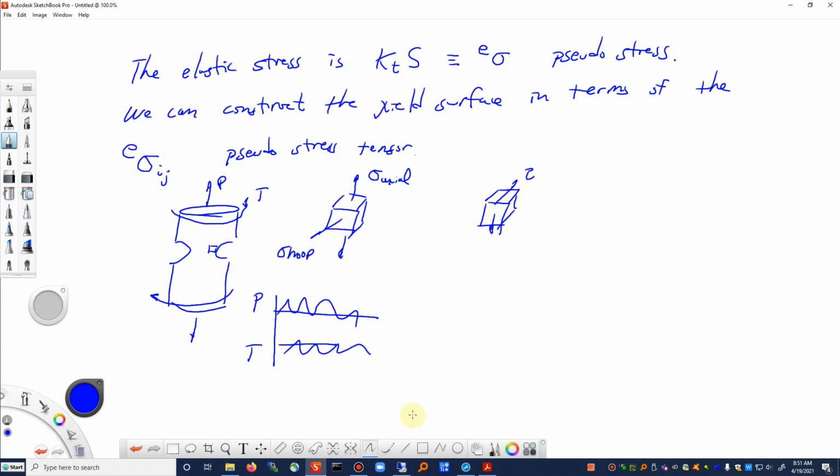If it's elastic, all I need to do is a single static finite element analysis of each of these individual cases and then apply superposition.